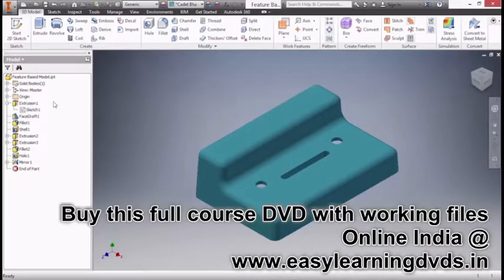And next, we can see we have a series of features, such as extrusion, face draft, fillet, shell, and others. The types of features that we see in this tree can be subdivided into two different categories. You basically have sketch-based features, such as this extrusion 1, which required a sketch to help create it. And there, as I hover on top of the sketch, you can see basically how that was a couple of rectangles perhaps put together with some dimensions on them.